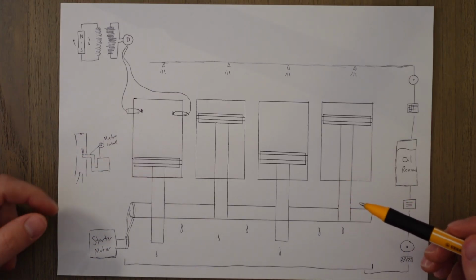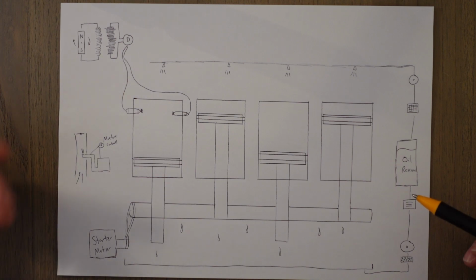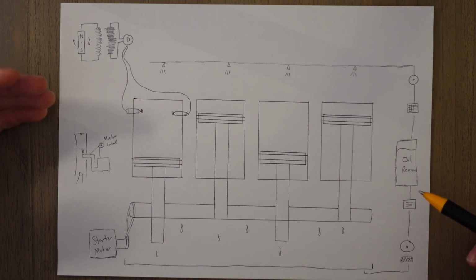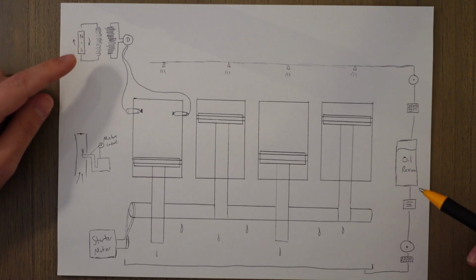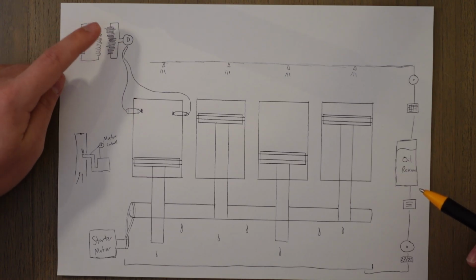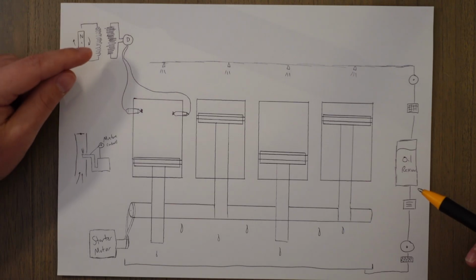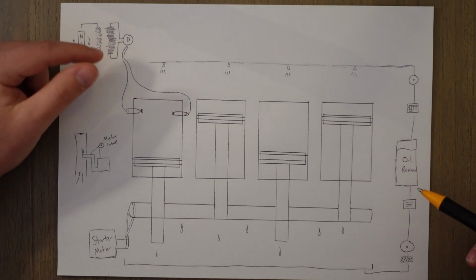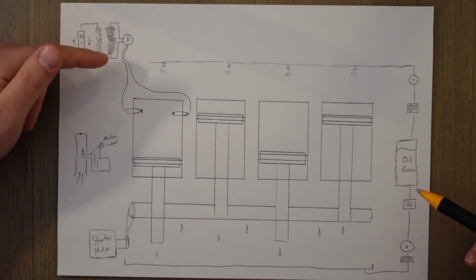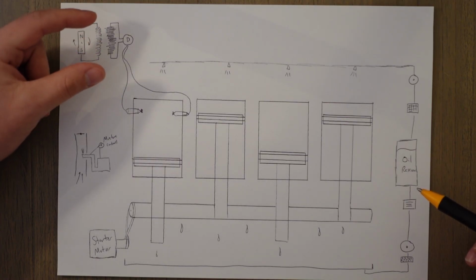Then we can disconnect the starter motor and the engine runs itself. We get the ignition system, which is used in the form of a magneto system. We basically spin a magnet and it induces a flow of electricity back and forth in a coil of wire. This coil of wire creates a magnetic field which interacts with another coil of wire which has more length of wire that is going to be affected by that magnetic field. This means a higher voltage.